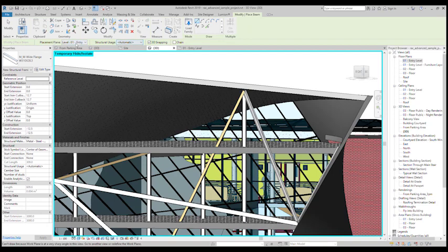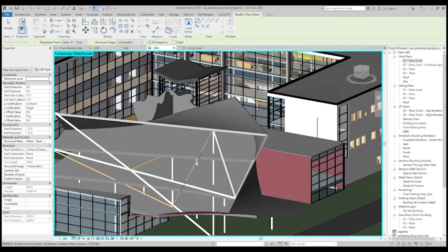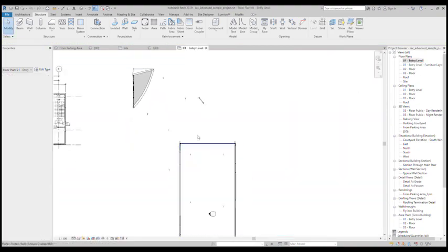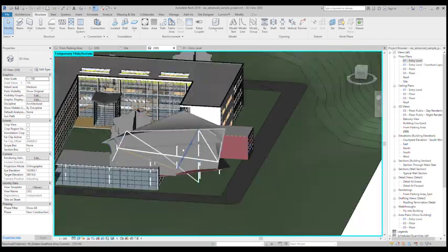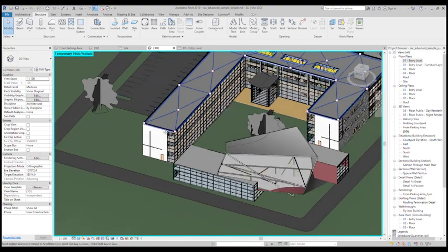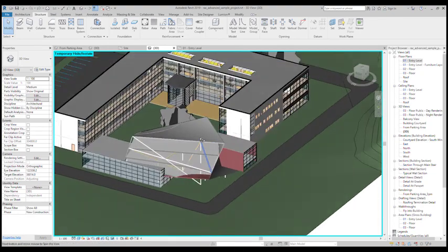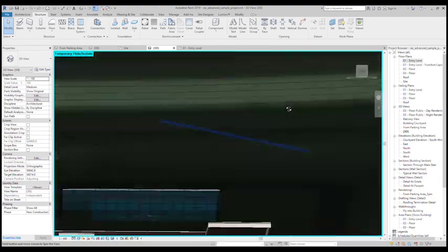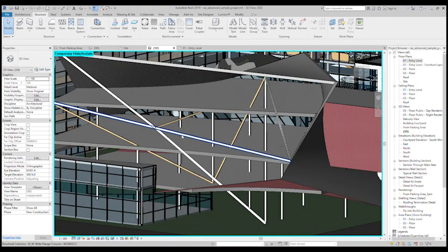Okay. Don't place them. So I like placing my beams and columns in 3D views because it's so hard in floor plans to place beams and columns. You don't know where they're snapping to. They place them at all of the weird places. Unless you're placing 100 beams at a specific level where you know you're going to, like inside this building, for example, in a grid, then you can do it in a floor plan. But if you are exploring or experimenting conceptually with a mass and its structural stability, maybe it's a good idea to just use the 3D snapping toolset.